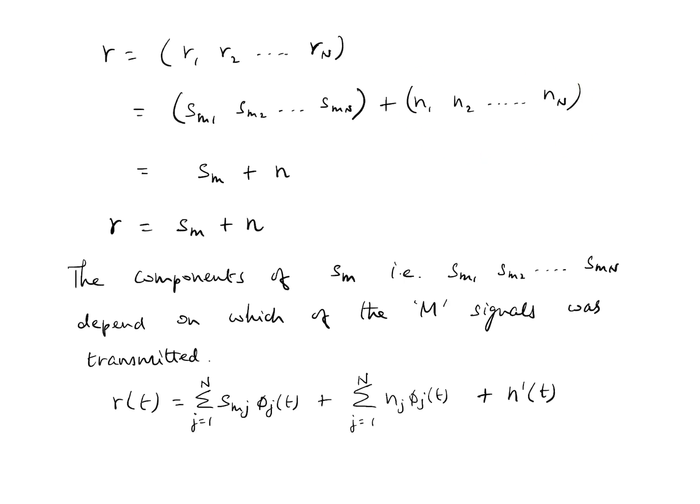Okay, but what we need to bear in mind here is that the noise signal that we take into consideration here represents only that noise which lies within the signal space, and that can be represented using the n basis functions. All the noise which cannot be represented using these basis functions, or which lies outside the signal space, is not included in these elements R1, R2 and so on.